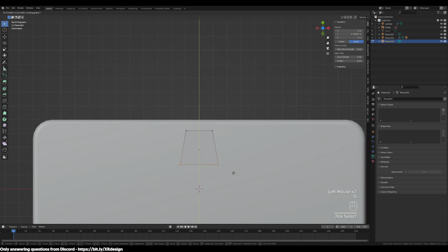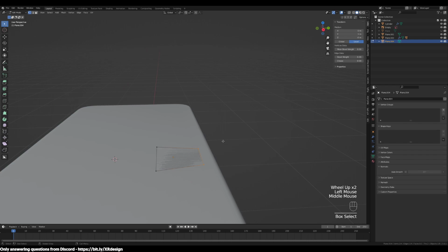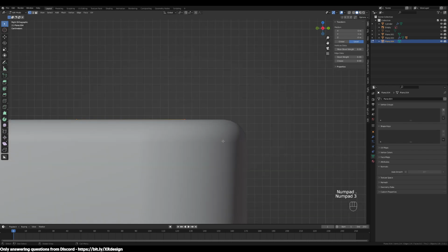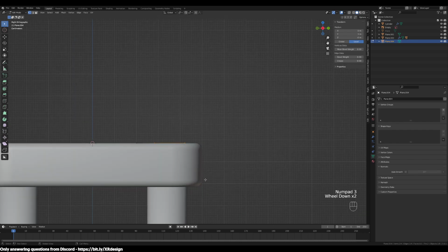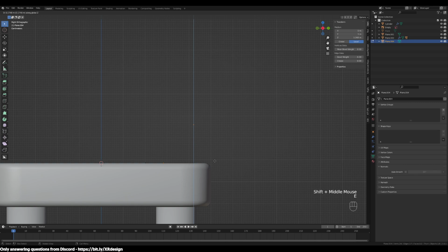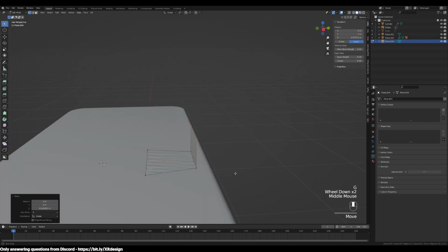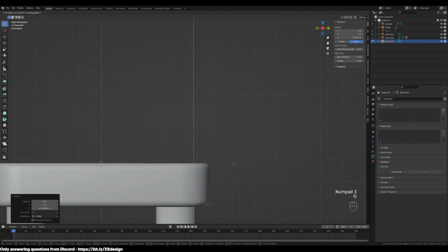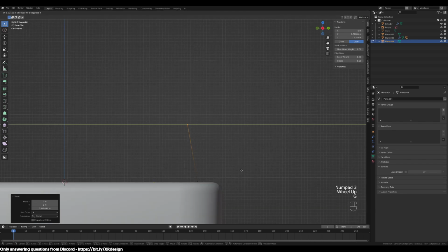And I'm just going to move the front of that stand a little bit upwards, like so. And then let's create the shape of that stand first before we add depth to it. So just select the two vertices here, and then go to side view, hit E to extrude. And I'm just going to extrude it along the Z, but we will move it forward eventually by this much, maybe a little bit more. Okay, and then let's move that forward.